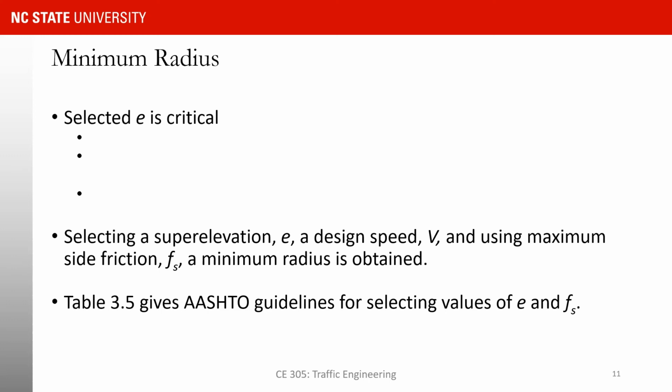What if the super elevation is too small? What's going to happen in that condition? Well, you need to have a very big radius, right? Or you need to reduce the speed. Otherwise, the vehicle is gonna fly out of the curve. So you're gonna have understeering, right?